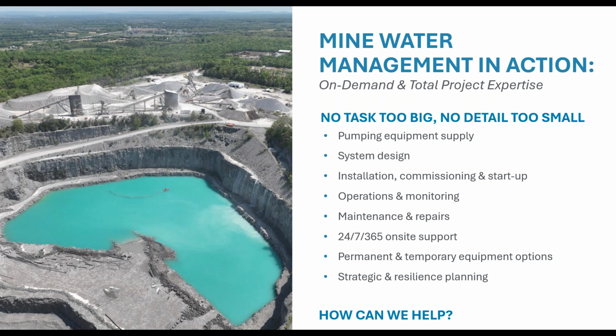If they're starting and stopping too frequently, or even snoring, snoring will lead to increased heat in the motor without the cooling of the pump fluid, as I mentioned, with clogging. And this could be an indication that the sump level controls are not correctly set or not being utilized at all. Quick fix here could be utilizing a VFD to ensure that the pump is operating near its BEP, or best efficiency point.